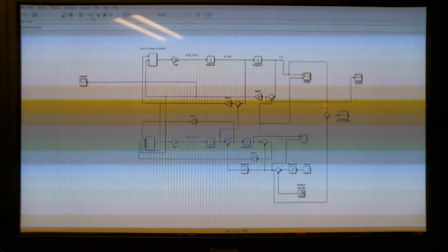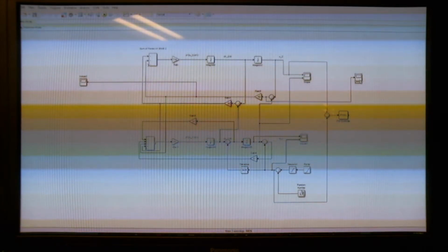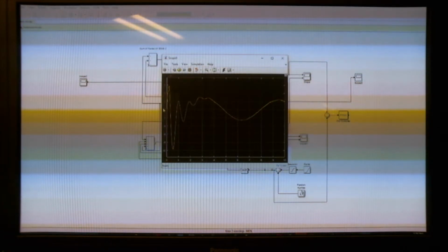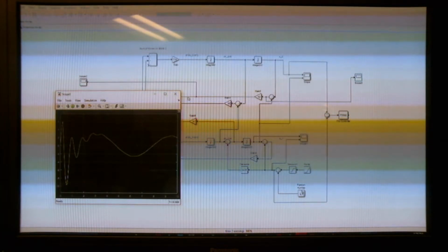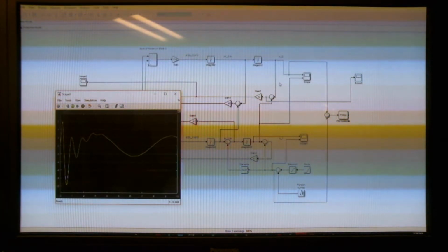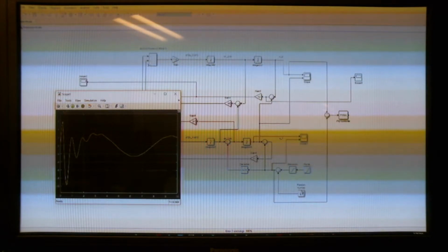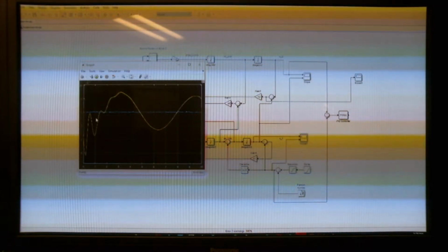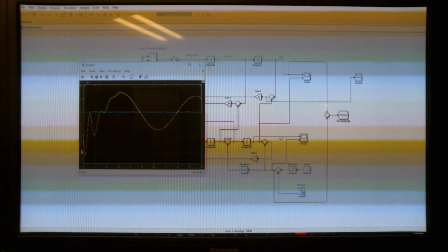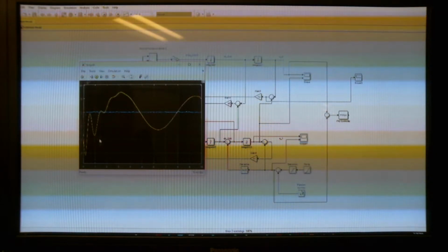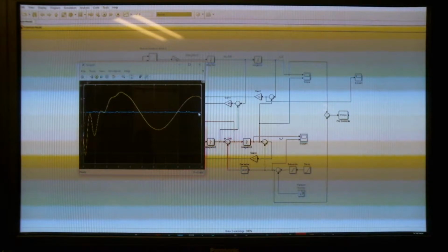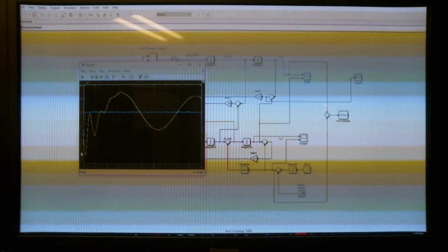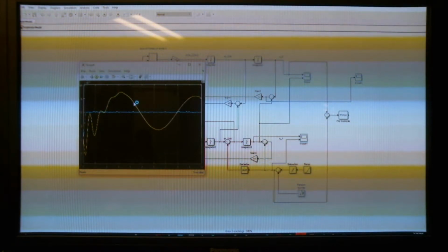Okay. So you can see response curves of your suspension components. This is, let's see, where is the one that we want? So you can see that while your wheel can move a lot, your body won't move that much, and you can evaluate design decisions based on the output of these plots.